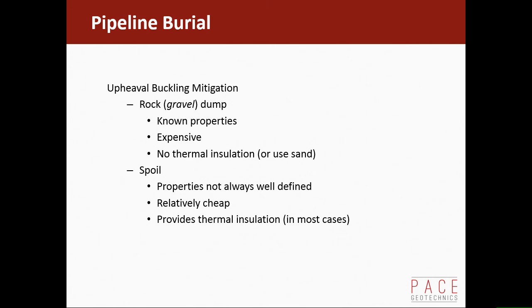There's also the advantage that they are relatively cheap. It's their material just to push back into the trench, and so in reality not that difficult to push that soil back into the trench. And they do provide thermal insulation, those backfilled soils. The exceptions might be if you've got a particularly coarse material or a very stiff clay which breaks out in big lumps. That might not give you quite the same level of insulation.